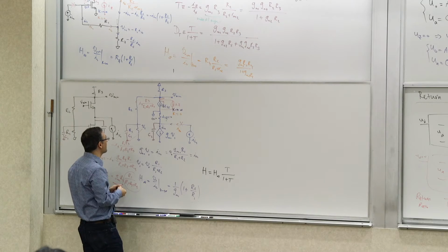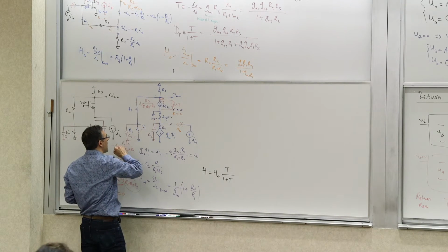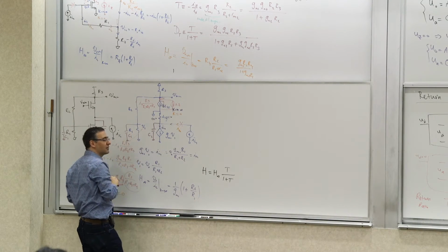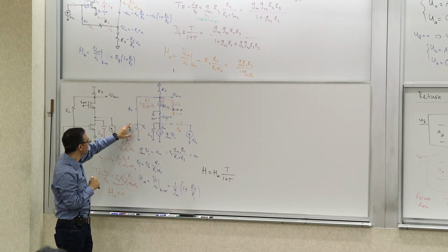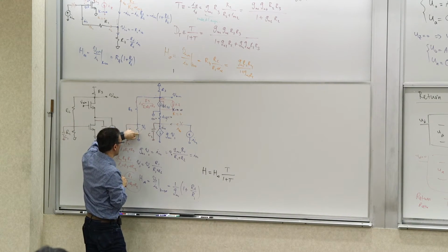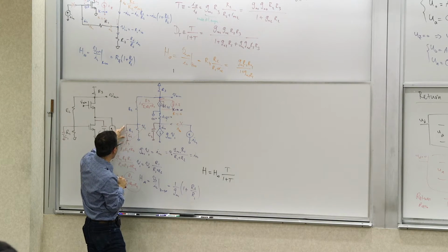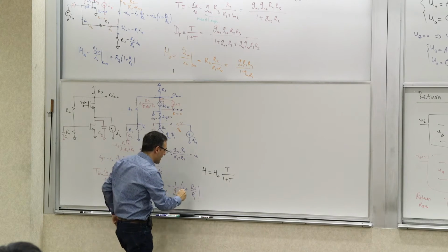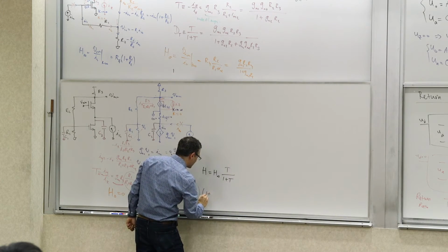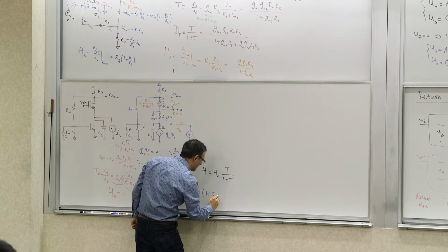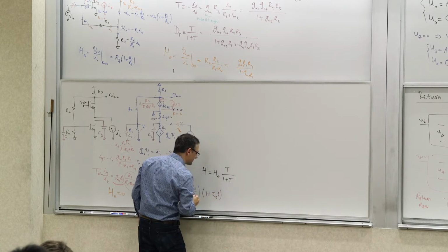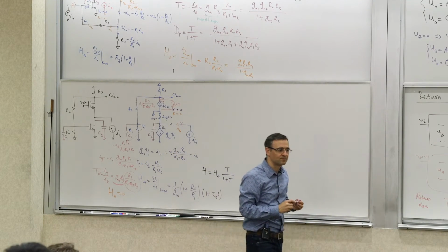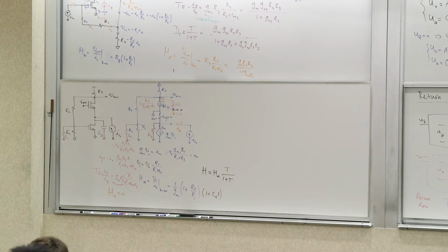So what is the thing that does play a role? It is this guy, because we saw before that this does play a role. Now your transfer function, when you go around, has a low pass response in your feedback network. And you remember what it did to the transfer function, right? We did this calculation before. It modified it by a 0. There was a tau z, it produced a 0 in this transfer function, if you remember from our previous example.